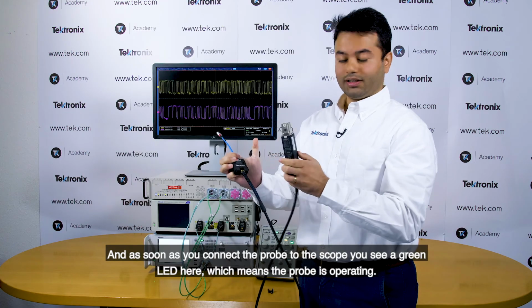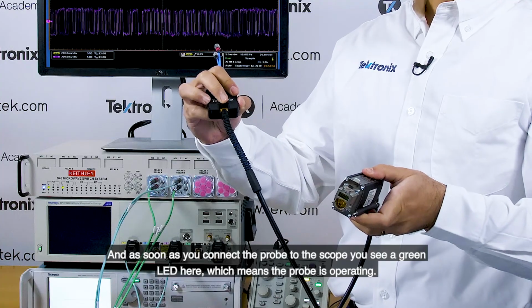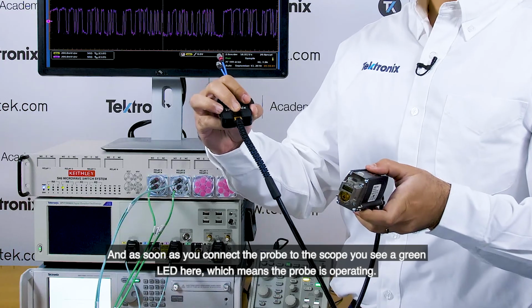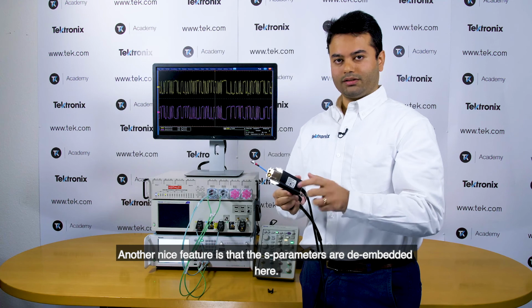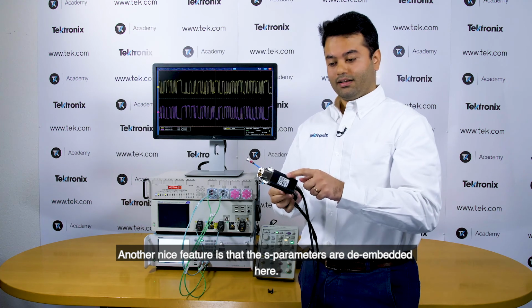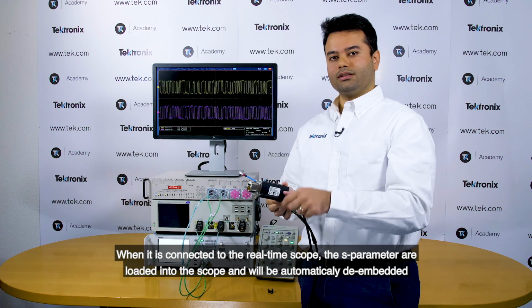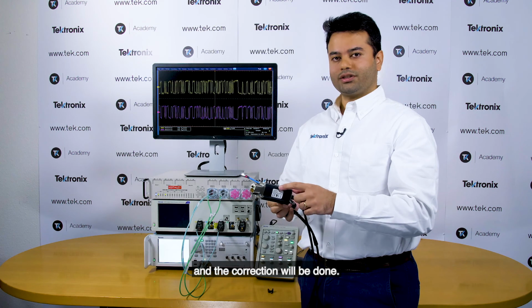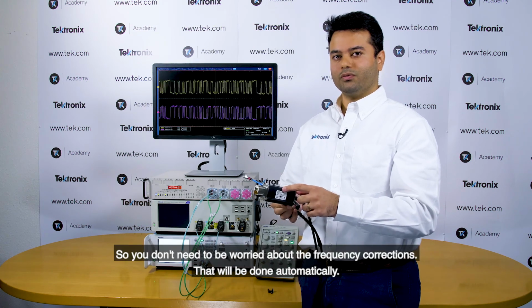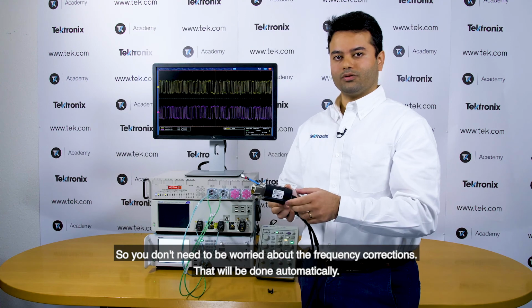And as soon as you connect the probe to the scope, you see a green LED here, which means the probe is operating. And another nice feature here is that all the S parameters are de-embedded. When it is connected to the real-time scope, the S parameters are loaded into the real-time scope and will be automatically de-embedded, and the correction will be done. So you don't need to be worried about the frequency corrections. That will be done automatically.